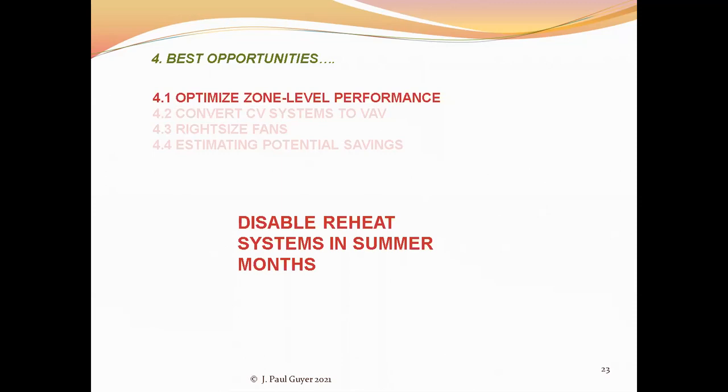In the summer months, disable the reheat system because it can be that it's not needed all summer long. And so there's no reason to keep heating water and pumping it around the building if it isn't going to be used for several months.